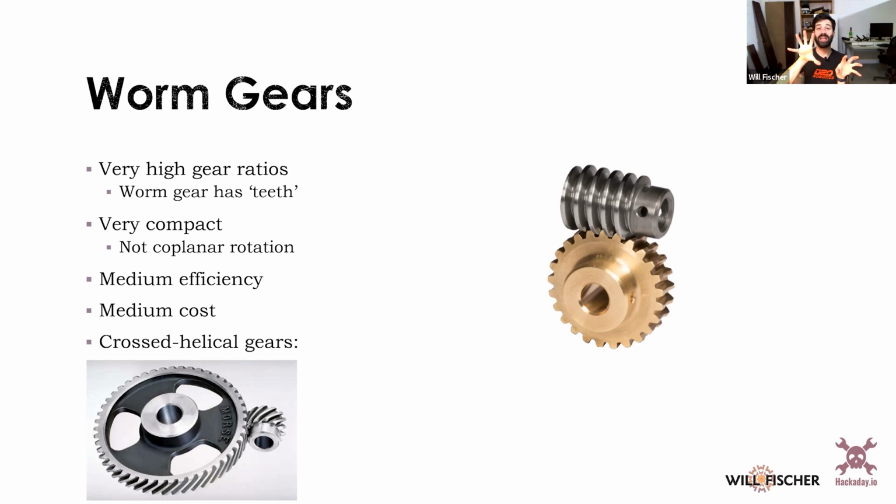So that means I need an 18-to-1 gear over here, and this thing is going to be huge. It's going to be massive. So there's just not an efficient way to do it from a material space perspective. You can't fit it all in there. Whereas this worm gear is super efficient. It's tiny, and you can get pretty high efficiencies. But I would say a normal one-start worm gear like this is probably going to be in an efficiency range around 70%. So that's not great, but it's not terrible, and they're not super duper expensive to create.